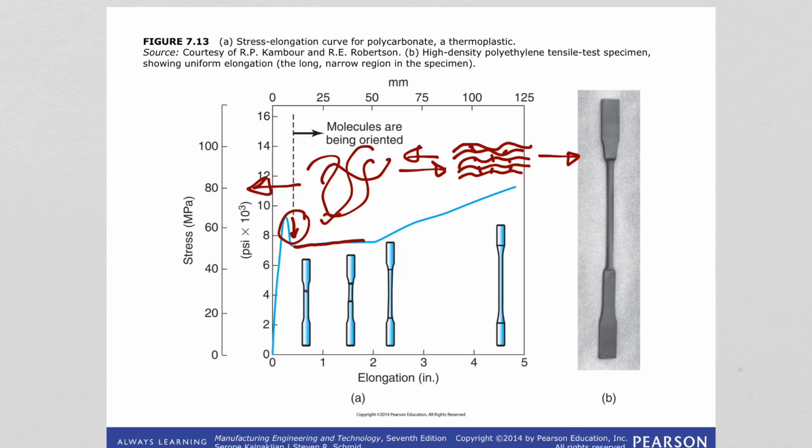So they are not getting stronger as metals. Therefore, you can keep the same strain rate with the same stress. Therefore, the stress is constant until some region where a more crystalline arrangement is happening, because the crystals are now arranging into more ordered structures, which causes a sudden increase, but still the polymer goes up until the fracture and elongates to a large extent here.